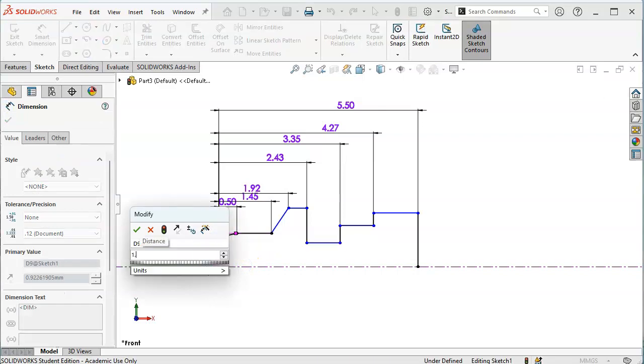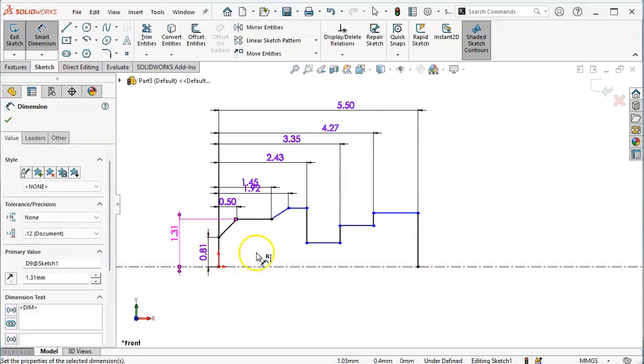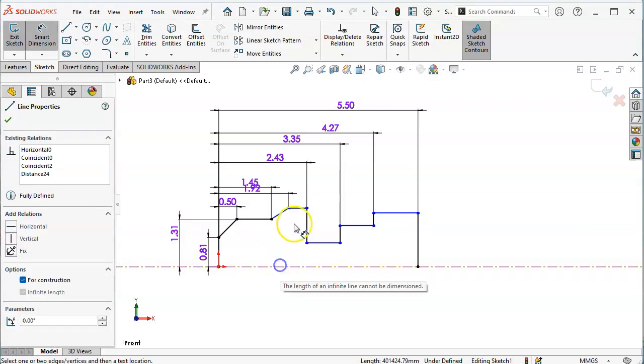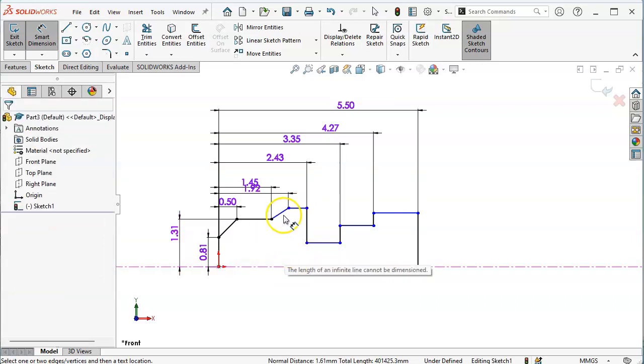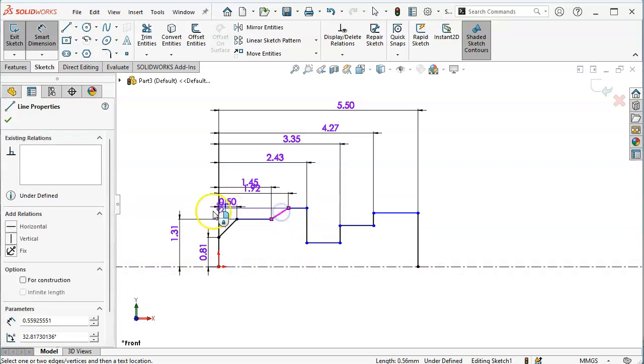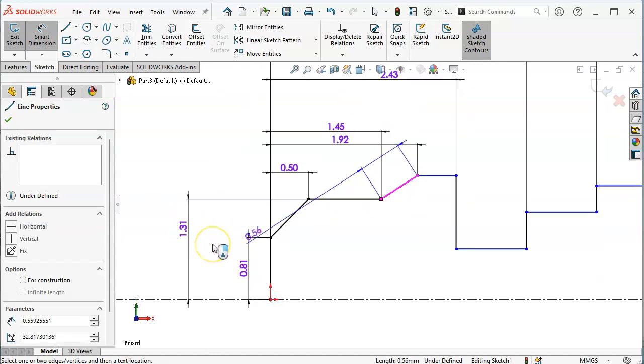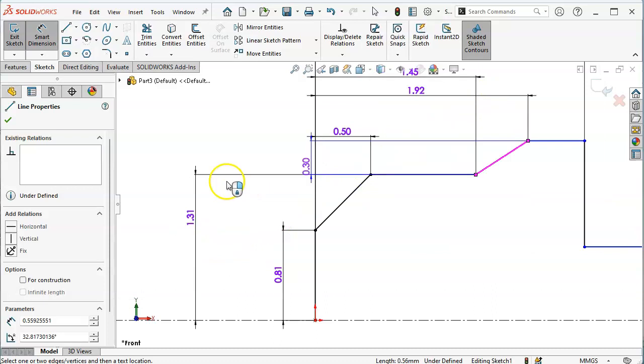And then we're going to go to 1.31, and then we'll go down to 0.69. Oh, actually, we need to go 0.69. I'm going to keep hitting escape. Yep, escape one more time. All right, so the reason that we have a smart dimension, I'm going to use the scroll wheel mouse to zoom up. And the smart dimension says, depending on which way you drag, determines the result.